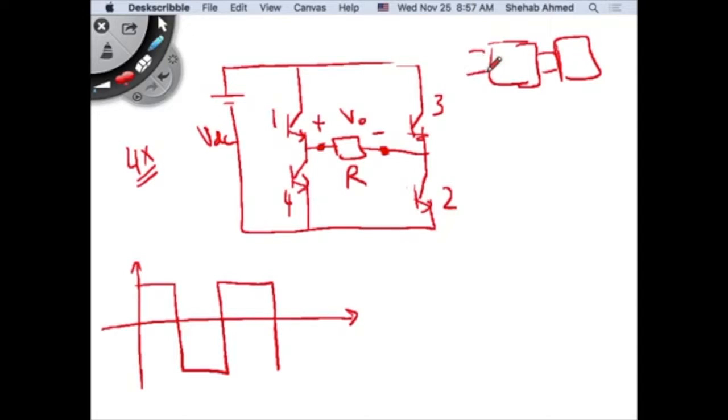right? If you boost 2 boost converters in series, so 12, you can multiply this by, let's say, 4. What do you get? 48. Multiplied by 4. No, it's closer to 200, right? It's 200, 200 minus 8, right? It's 192 volts, right? So you can get your 180 volts.